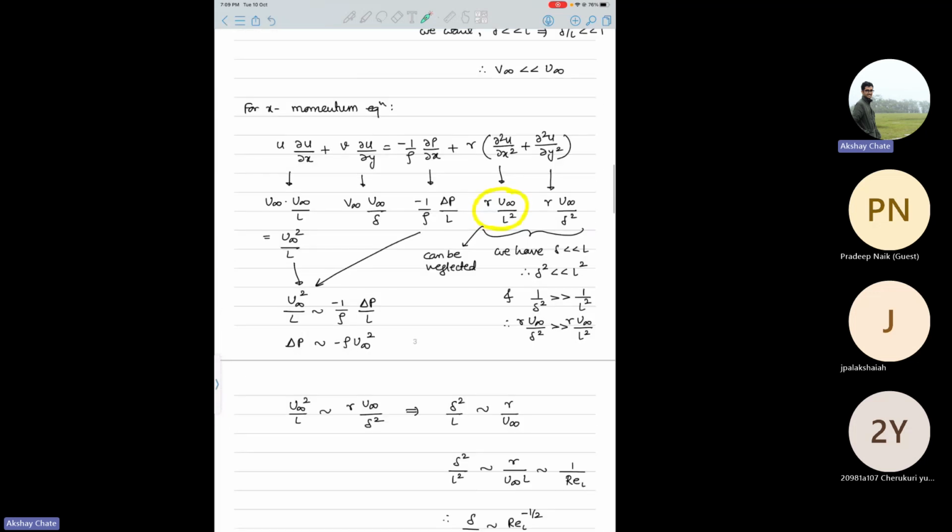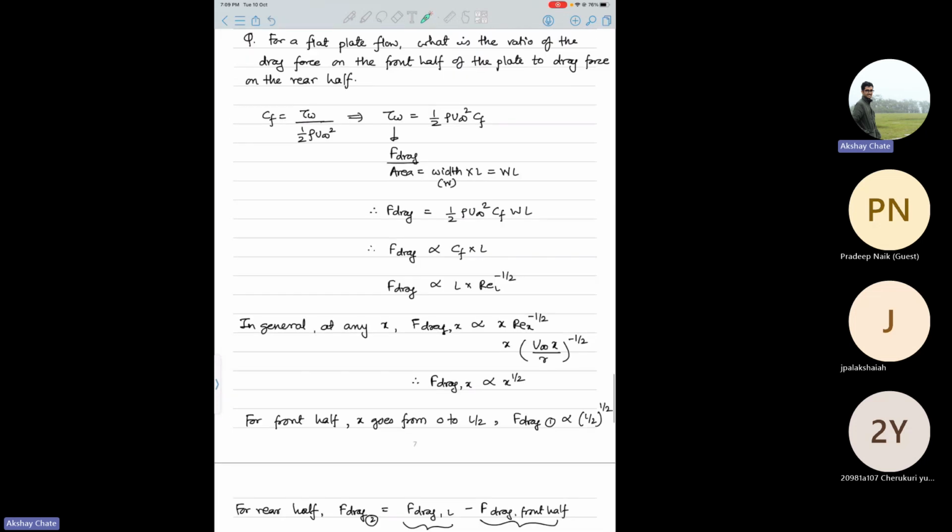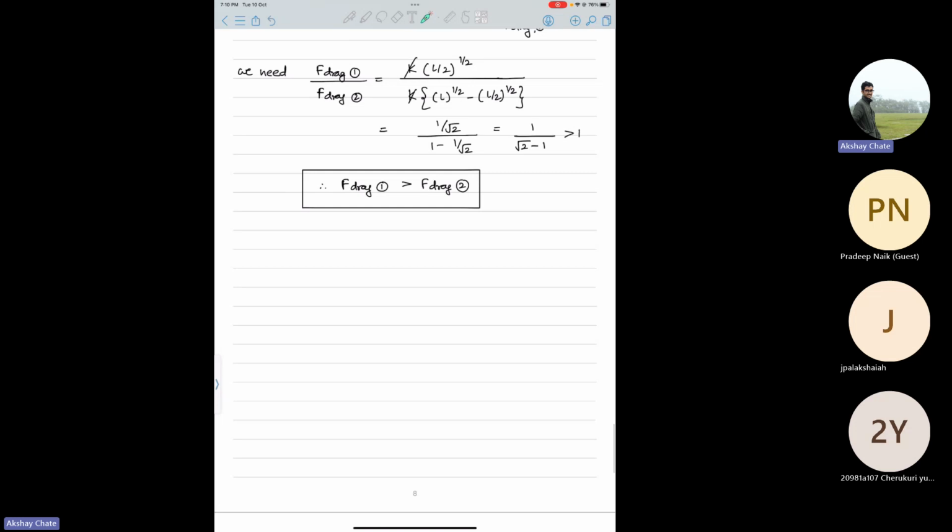And one important note that you should remember is this boundary layer analysis. I mean, this is a typical interview question. So what did you say? In the fully developed flow, the shear force is not there? No, it will be there, but it will become constant. Constant, right? Yeah.